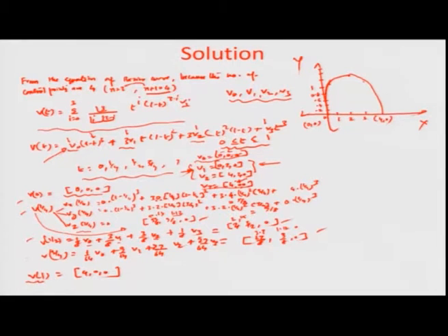So, if I looked at the geometry, it is going to be like an arc in this manner, and that is how the Bezier curve would look typically in this particular case. So, the Bezier curve is defined by a polynomial or polygon described through connecting all the different coordinates, and if I looked at whether the condition of the Bezier is being set here, namely the first line segment of the polygon of a curve would align with the tangent to the first point, and the last line segment would align with the tangent to the last point.